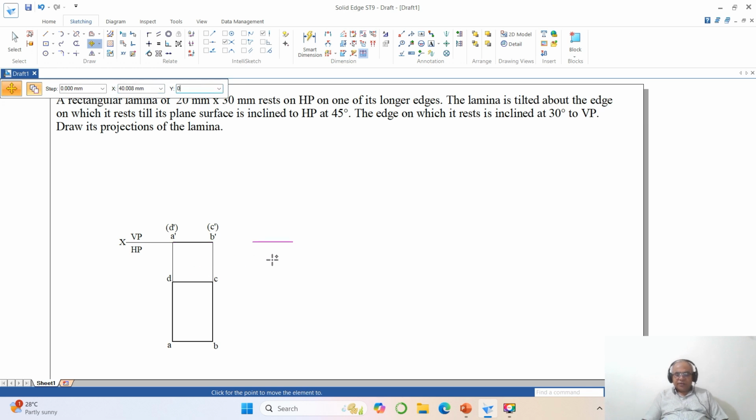So I don't want to have the display in y direction, so you take this and keep it wherever you want, and this distance can be anything. So then I need to rotate this, so go to rotate, disable copy, select this line. Now I want to rotate with reference to this. To rotate with reference to this, I need to enable endpoint now. So take it on endpoint, then this endpoint is rotated by an angle of 45 degrees. So you type 45. Since I have given positive, it moves in anti-clockwise direction. But I want to take it to the top. Take the cursor here and click.